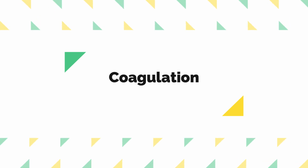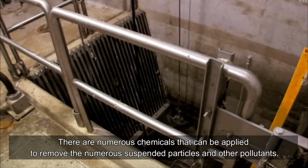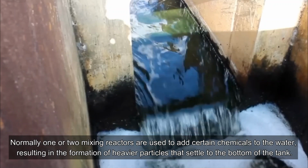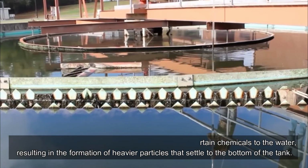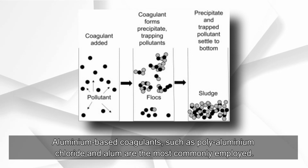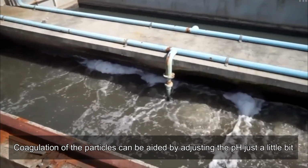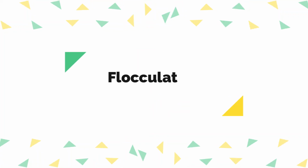Coagulation. There are numerous chemicals that can be applied to remove the numerous suspended particles and other pollutants. Normally 1 or 2 mixing reactors are used to add certain chemicals to the water, resulting in the formation of heavier particles that settle to the bottom of the tank. Aluminium-based coagulants, such as polyaluminium chloride and alum, are the most commonly employed. Coagulation of the particles can be aided by adjusting the pH just a little bit.